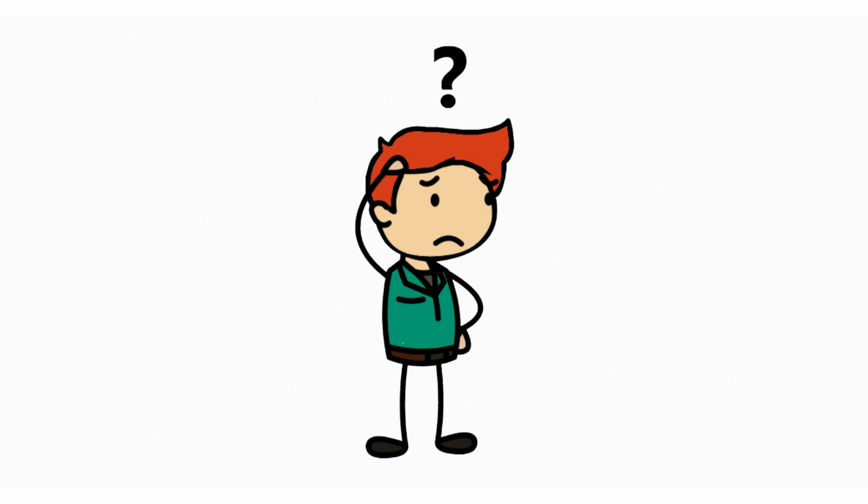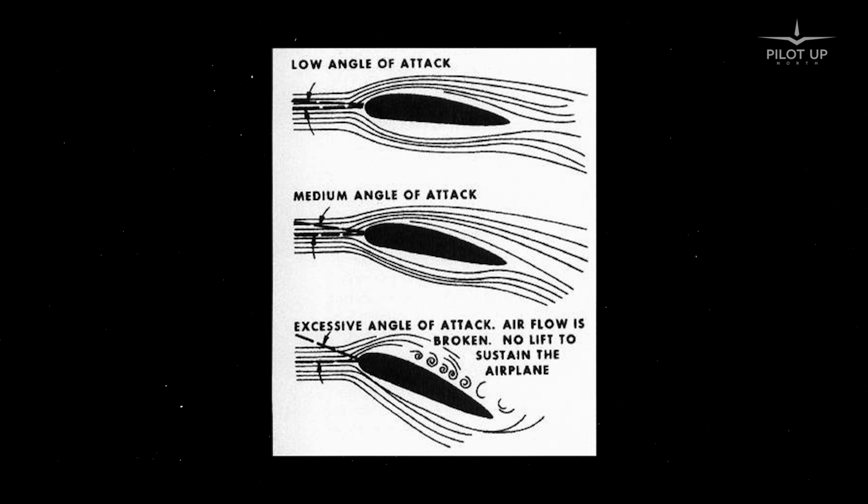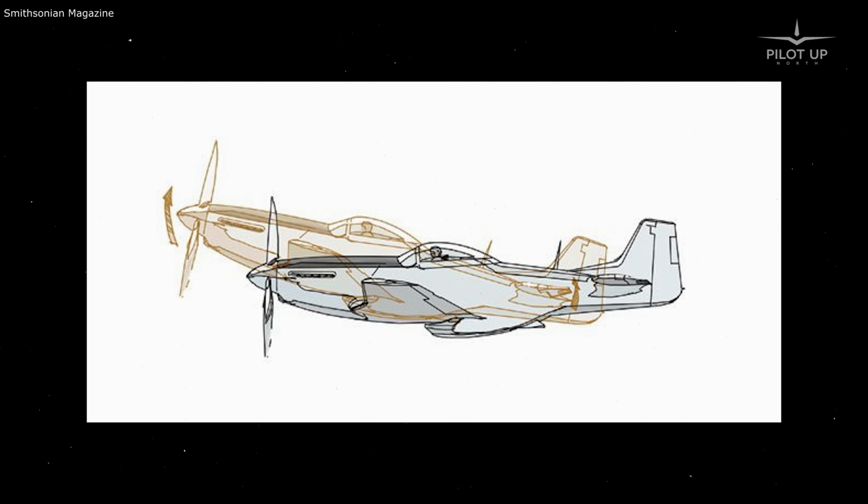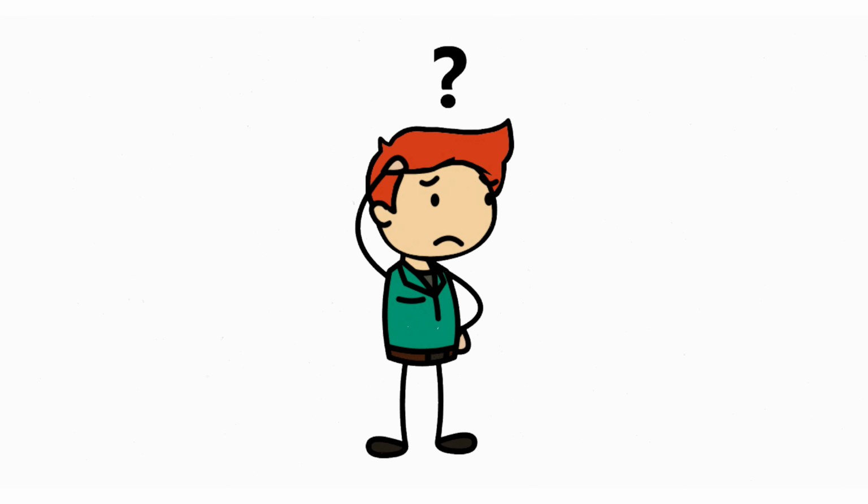So, following up, how to increase the lift of the aircraft with the angle of inclination of the wings? Very simple, just increase the angle of attack by pulling the control stick or yoke, depending on your aircraft, towards you as if you were commanding a climb. But Gilberto, why didn't you say so from the beginning? Why go around to say that all you need to do is pull the control stick commanding a climb?